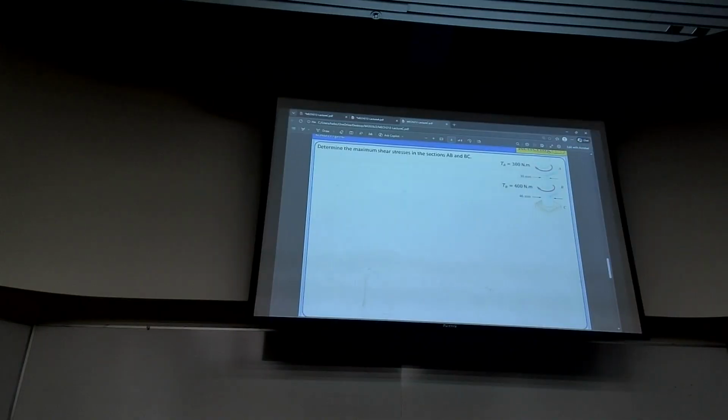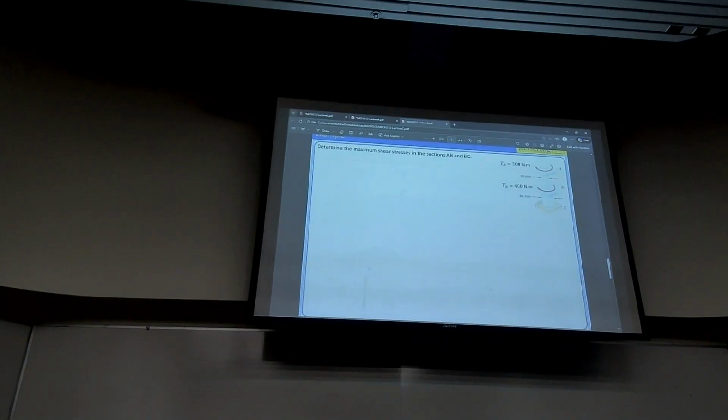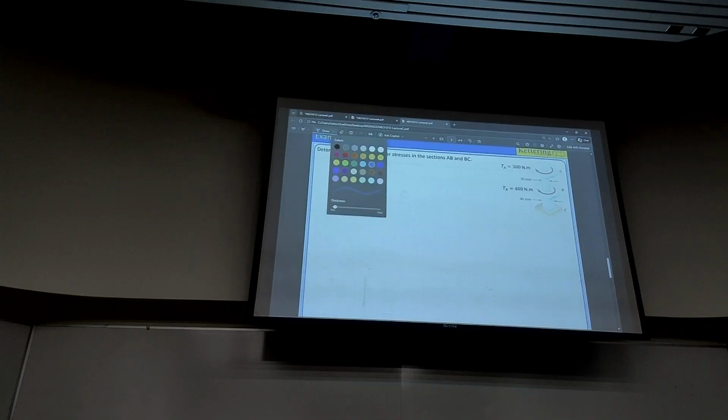All right. Mossy is asking for shear stress and it's about torsion, then we should immediately write down the equation for that. So please give me that. Torsion for shear. Tau equals TR over J. When you say equation, two sides, the left. Shear tau equals. So tau equals TR over J is the equation as you said.